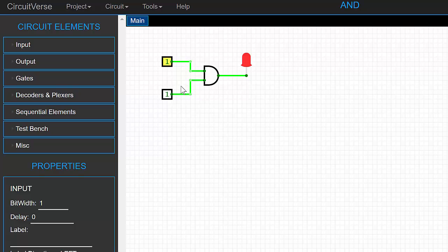Now in your workbook, you need to actually record this within a truth table. And within a truth table, all you need to do is to go, let's look at all the combinations that could actually happen. So 0, 0, it's off. So you'd write down a 0 in your book. You'd switch one of them on. No light is on. Switch it off. Switch the other one on. No light on again. So all 3 of the first ones would get 0s. And then finally when 1 and 1 are on, this would actually be set here to be completely on.